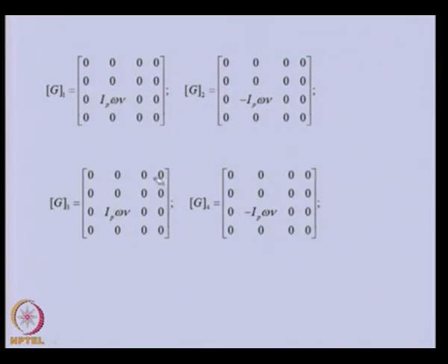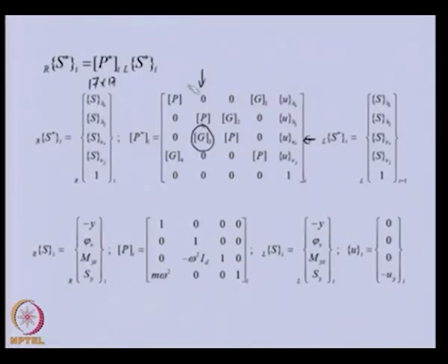Most of the terms are 0 except the ones belonging to the gyroscopic couple terms. Now you can see that the overall point matrix is of this form. Now, we can take up an example to illustrate how we can use it, and we can calculate the whirl frequency.